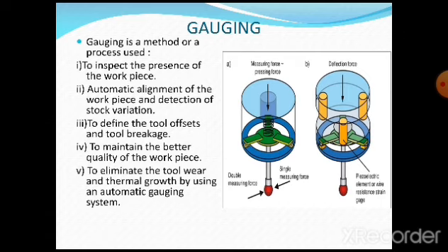So we need to understand that as CNC machines are basically automatic machines, we require to provide an automatic gauging system, okay, with the help of one device known as a trigger touch probe. As the name itself indicates, again it is an electronic measuring system by which it is possible to detect the position of the workpiece, whether the workpiece is mounted or not, or is there any problem with the workpiece itself regarding its surface. Okay, and even a finished job can also be measured properly with the help of the touch probes, which we are going to understand now in this presentation.